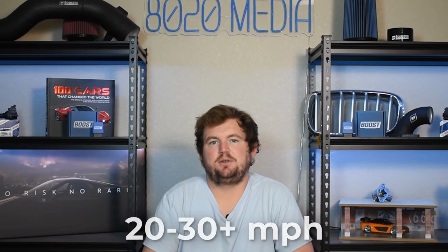So most commonly, overheating would be experienced with this issue if you're going at extremely slow speeds, say stuck in rush hour traffic, or letting the vehicle idle for extended periods. Generally, the cooling fan on most engines is not required once you're up to 20, 30 plus miles an hour, as you then have enough air moving over the surface of that radiator.